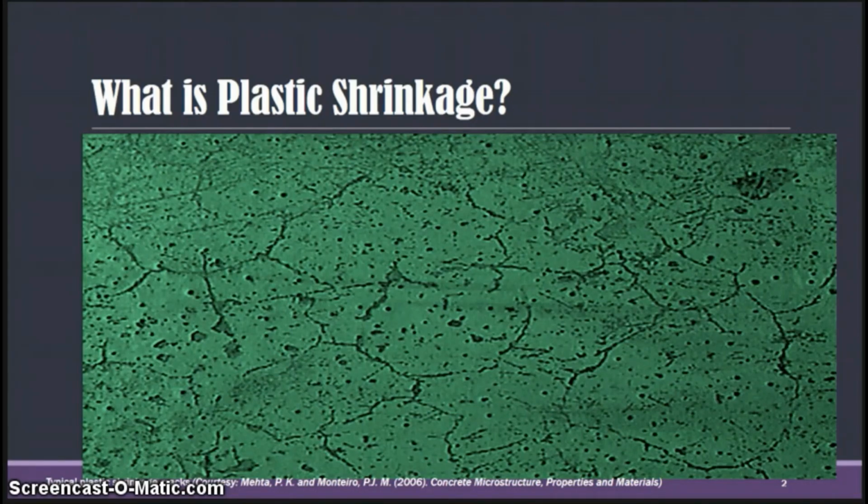The plastic shrinkage, or the shrinkage simply, is also called the pre-hardening or pre-setting shrinkage. It happens majorly because of reduction in volume of the concrete, and the major volume change happens because of loss of water. If the concrete is not completely stiffened and it loses water, instead of forming voids, it will form cracks.